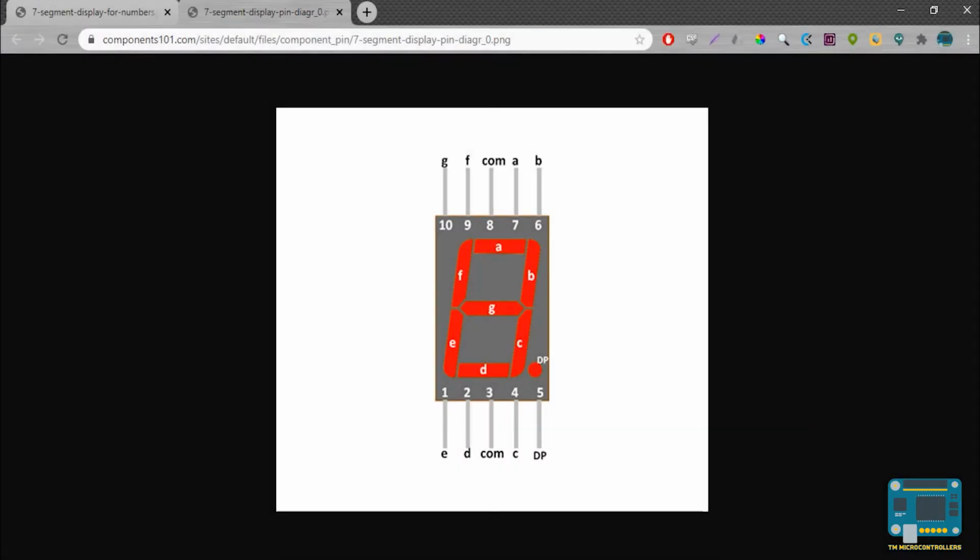Okay, so just a review on 7-segment displays. There are actually two general types: the common cathode and the common anode. Basically, a 7-segment display is just a series of diodes or LEDs wired together, and through a different combination of which LEDs to turn on, you can generate whatever digit you would like, that's from 0 to 9. You can also display letters in the hexadecimal numeric value like A to F, but here we'll limit ourselves to the digits 0 to 9.